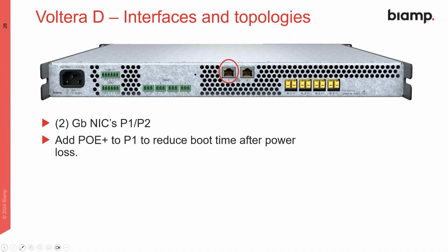And once mains power is restored, only the amplification portion of the loudspeaker controller needs to boot up, which takes about 10 seconds, as opposed to waiting a couple minutes from a completely cold start for the entire chassis to power up. So pretty good case for backing up your network switch, which has PoE plus output capability, to keep the amp alive, or just have it wake up quickly depending on the use case for your system.